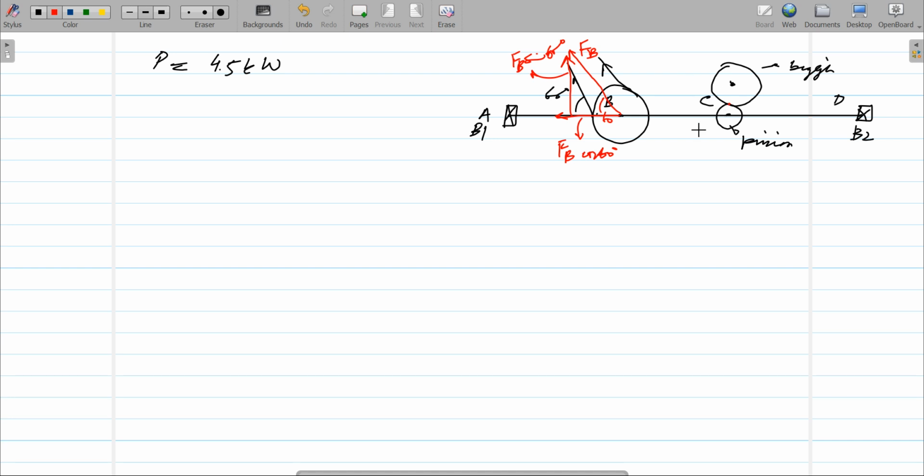Similarly, in the case of gears, as we discussed in the gear section, there is a line that passes tangentially to the base circle. So this is the line that you have to pass through, and there is a horizontal line, that is this. The angle between the horizontal line and this tangential line is called the pressure angle of the gear, which is phi. This is the case when the gears are upside down, or you can say top and bottom.